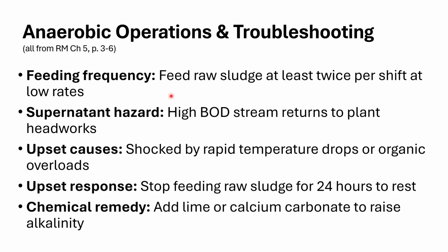And that's why we sent somebody out there, a junior operator, on that catwalk of the primary clarifier. Remember the sludge judge? They wanted to take a look at the sludge column, at the sludge blanket, to make sure that it was okay to start feeding that sludge to the digester. So that's what we're doing. We're managing the sludge blanket, plus we're also managing the digester.